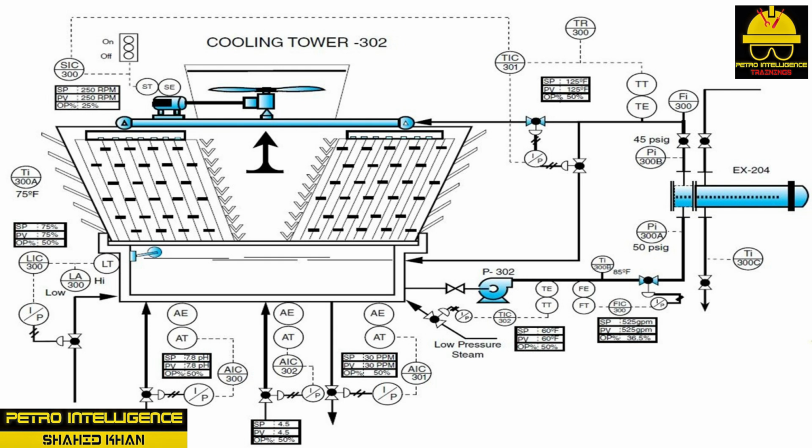Cooling tower fan is mounted on the top of the water distribution pipe in the center of the cooling tower. A local controller and on-off switch are located near the motor. The motor is designed to run at 250 RPM and can be adjusted depending upon need. Plenum is the open area directly under the fan. In an induced draft, cross-flow cooling tower, the velocity of the air creates a partial vacuum under the fan as it expels the vapor-enriched air.